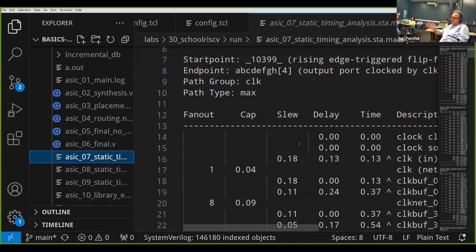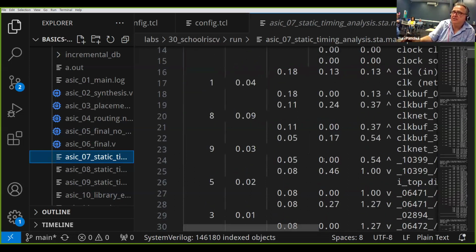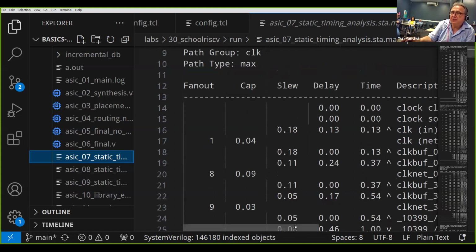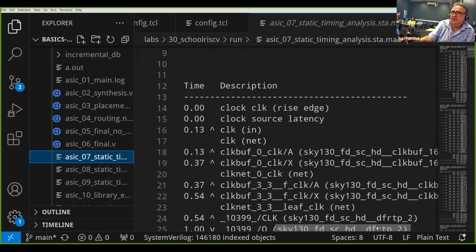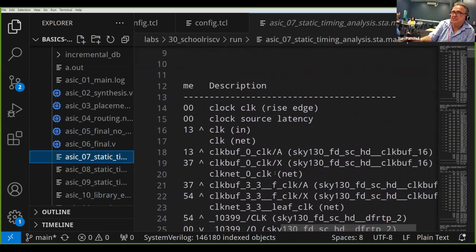So the clock stores results when you finish computation and everything becomes stable. Then it stores in D flip-flops. Then the next cycle starts, it computes something, stores in D flip-flops. Next cycle starts, computes something, stores in D flip-flops. So in order to do this, you need to have all physical delays fit into your clock cycle. And now here you can see the longest path through the cells. This is called static timing analysis.